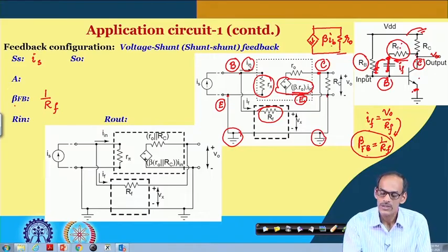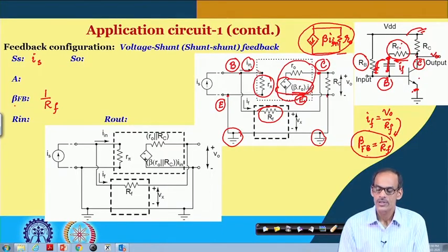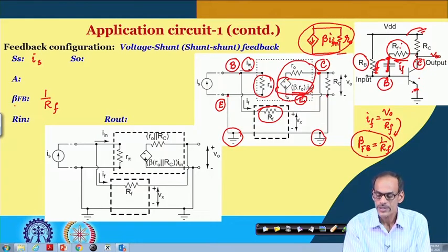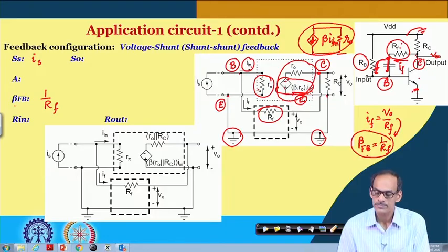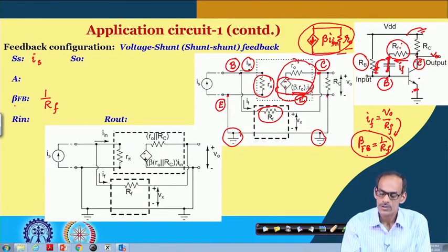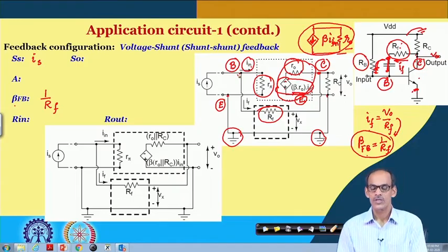Now, this I b is the same as I in. So, probably you can write this as I in, and this circuit, now an equivalent circuit, we are writing here in this form, which is the Thevenin equivalent. So, in summary, we can say that the internally developed voltage here is beta into R naught into I in. Of course, the polarity of this current, positive current, is from collector to emitter. So, that is why we do have a minus sign here and a plus sign here, and this R naught is directly providing the Thevenin equivalent resistance.